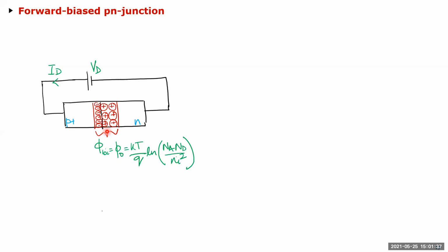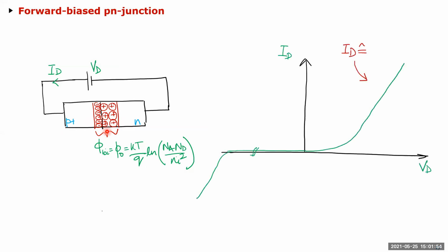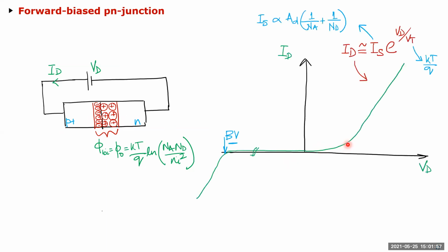So you'll see that, whatever this 0.45, 0.7 volts, most of it, but while we are breaking the barrier, there is a current, right? You have diffusion current, mostly diffusion current flowing during that time. And as we keep increasing the voltage, after you break the barrier, it just exponentially increases with reference to the voltage applied across it. So the typical expression is actually one minus this, but approximately it's the saturation current times the exponential of this voltage across it, across the P type.